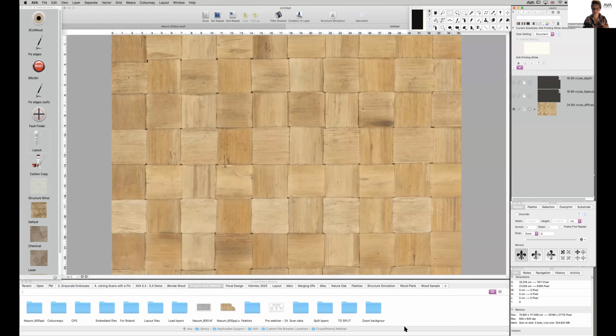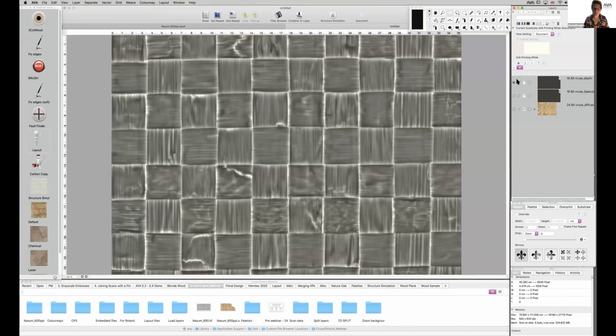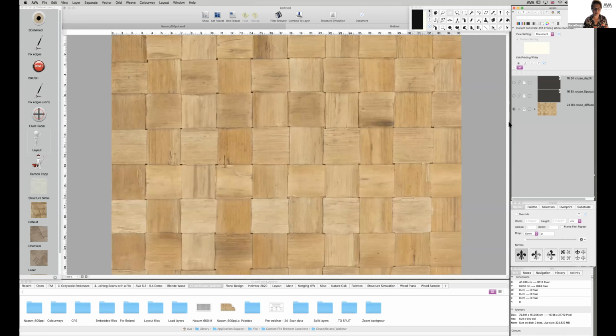So as you can see, I've now got the file here from Martin, and we can import all of those scans, all of that data that Martin's just scanned in. So we get the height map, which I've inverted. You'll notice that looks a bit different from Martin's. I've inverted it because AVA uses the dark side for the height and the light tones as the low marks. So just to explain why that looks a little bit different from Martin's. And then we have the highlight and the diffuse image. So all of this data is imported on open. It opens and merges the document in one go.